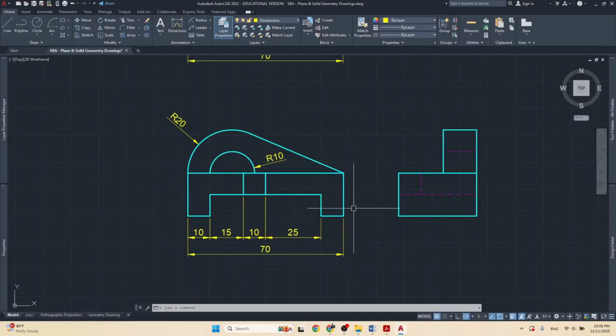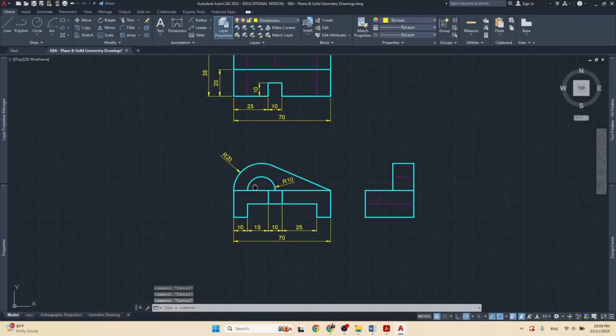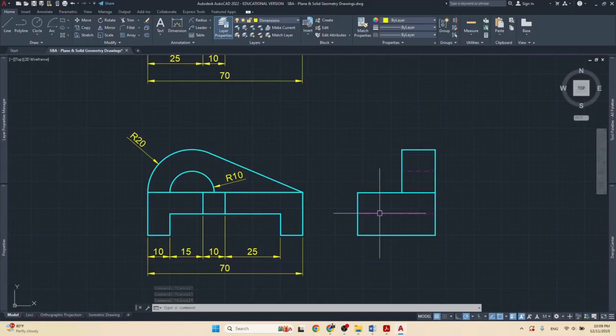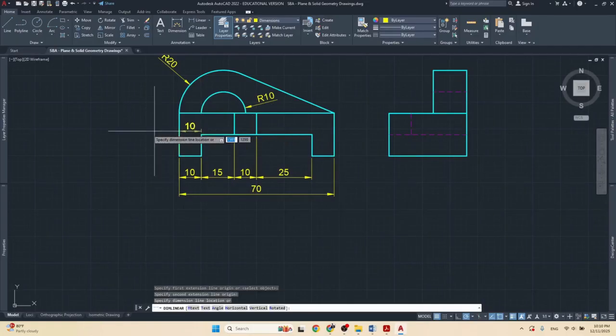I can also show the height of this piece, this length. And the reason why I want to do that is because I cannot show it from over here, because it would be hidden. It would be measuring a hidden detail, and we can't do that. So we need to dimension these distances from here. Well, this line come all the way up to here, come across like so. And because my last measurement is from here, then I can't say 10 from the object, I have to say 20. So 10 will bring me here, and then the other 10 will take me out here. So let me say 20, boom.